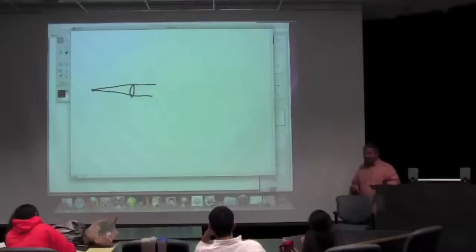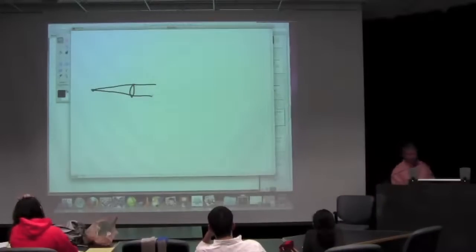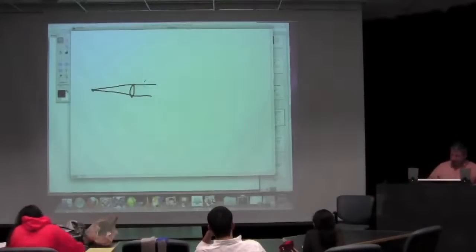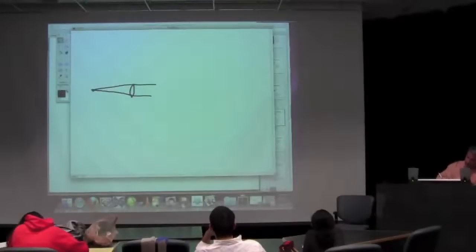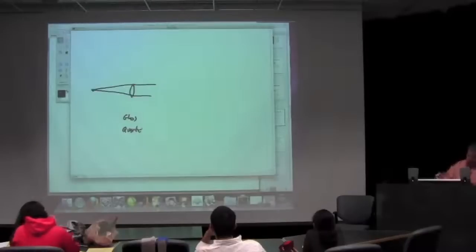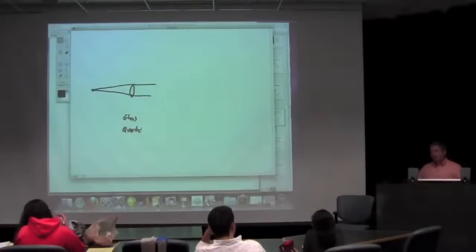Whatever my optic is made out of, if it's made out of glass, I can pass easily out to 1.1 microns, further. If I want to go much further, glass starts to break down a little bit. So you could go to different materials. Let's talk about that for a second. You could use just optical glass. You could use quartz for your lenses. Quartz tends to have a higher transmission as you get further and further out in the shortwave infrared.